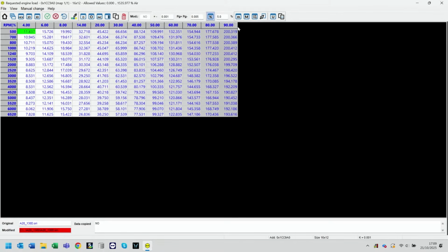As a tuner, we can apply quite simple logic here and see if we have effectively 0 to maximum torque as a percentage, it's a little bit like your throttle. If I've got 50% pedal, I'm probably going to have about 50% of my torque. Now, that's not a true one-to-one calibration in there, but it's a good tuner's logic to use when looking at these ECUs.